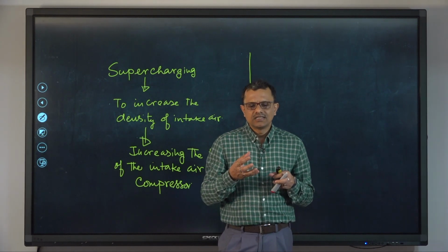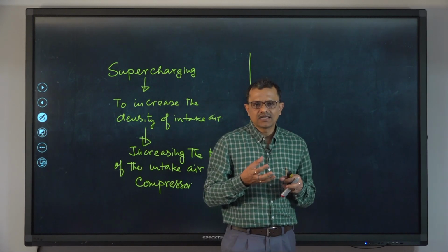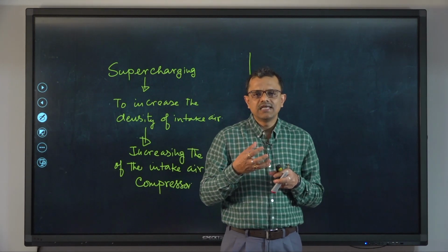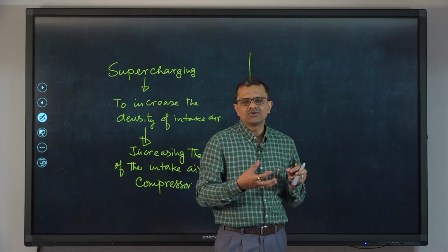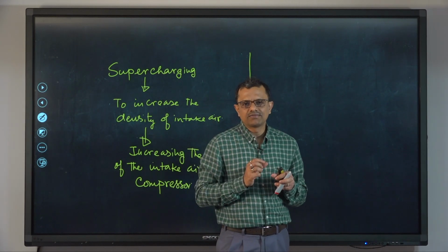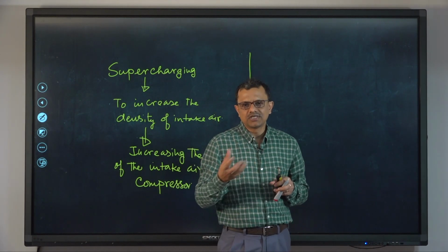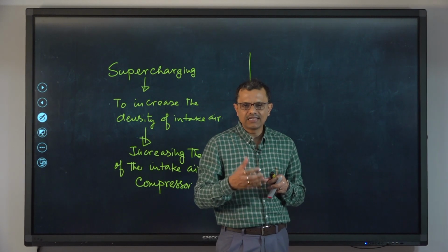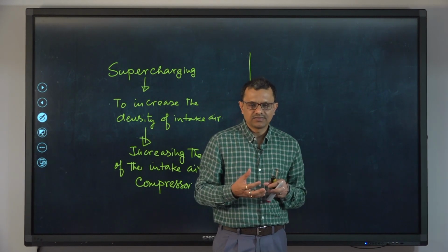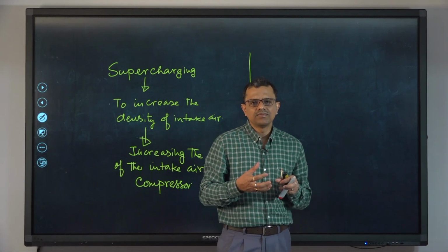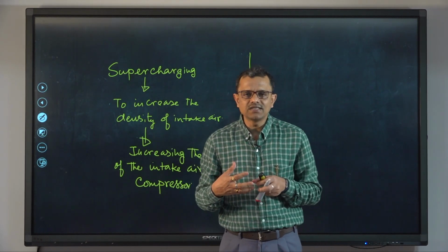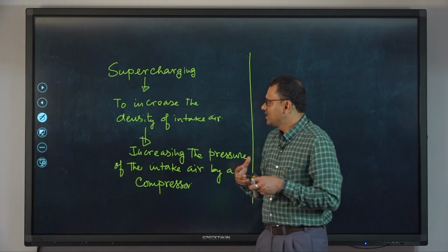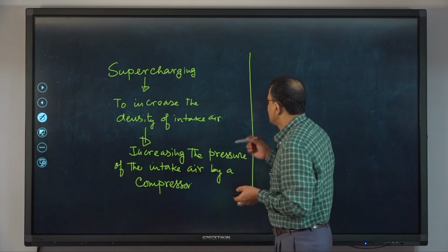And there may be a case that can we use the exhaust gases of the engine itself to run the compressor through a small turbine, and that is called turbocharged. So, it can be mechanically charged or mechanically driven compressor, or we can have a turbocharged system.